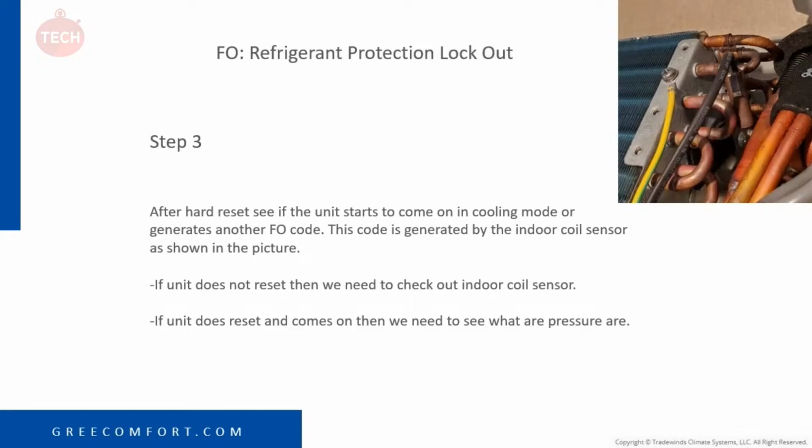If the unit does not reset, then we need to be looking at the indoor coil sensor. The indoor coil sensor would more than likely be open, and that would prevent the code from resetting. If the unit does reset and comes on, then we need to see what our pressures are and kind of go from there.